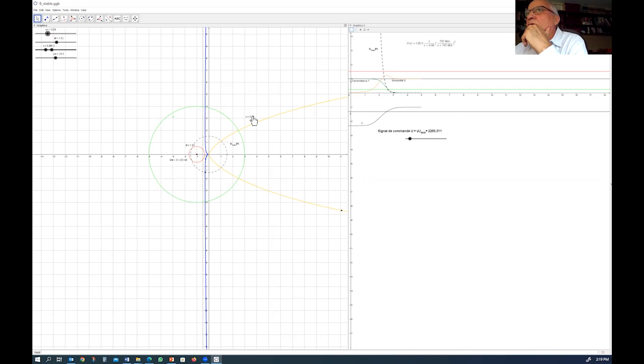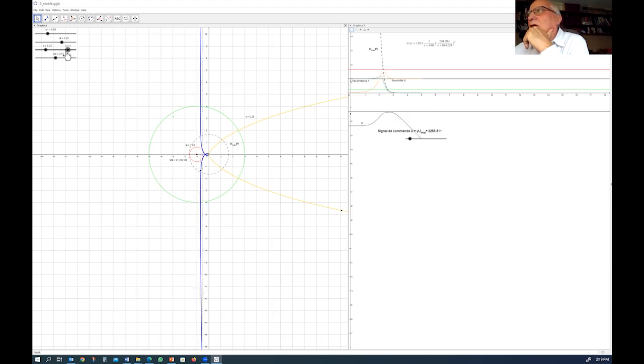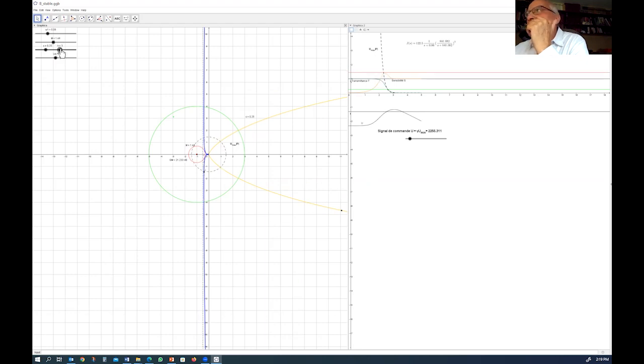And what you see here is U, the input to the plant, which means I'm going to adjust so I do not exceed the, you see here, my U max stays under a certain value. Okay, so this is adjusting, and we keep adjusting the parameters. And in fact, this can be done very easily. As you can see here, the blue line is the line of -1/2, at which my Nyquist is basically here.